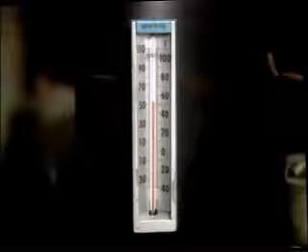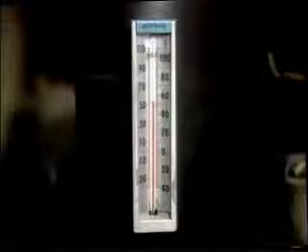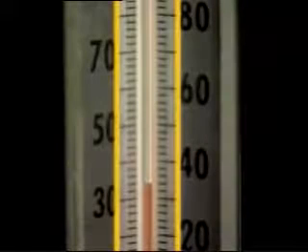A thermometer is a basic temperature measuring instrument that's often used in industry. One common type of thermometer is the fluid or liquid in glass thermometer. Fluid thermometers work on the principle that most fluids expand when they're heated and contract when they're cooled. The fluid responds to increases in temperature by moving up a capillary tube. It responds to decreases in temperature by moving down the tube. Temperature is indicated by the scale, which is usually either etched onto the tube or attached to the tube.